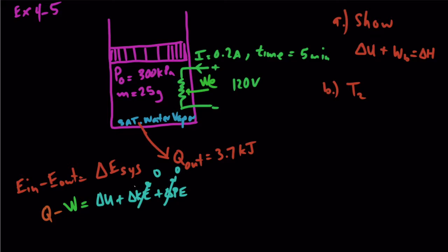So you have pretty much a non-existent velocity there, or one very close to zero. And for potential energy, we're not assuming large movements or increases in height, and we're not given any heights. So there is no way of determining the potential energy due to this cylinder going up and down. So basically Q minus W is equal to delta U.